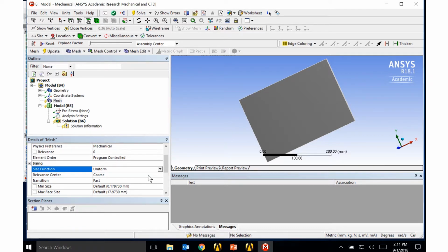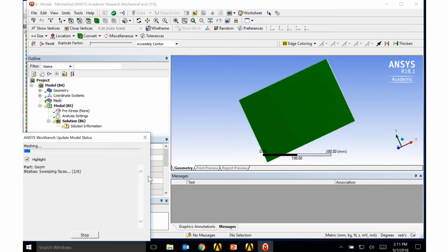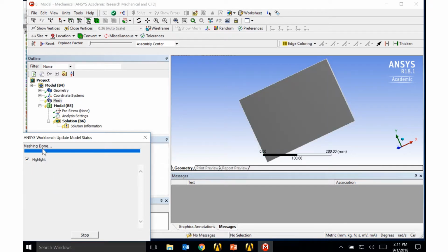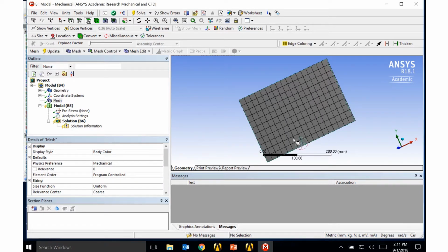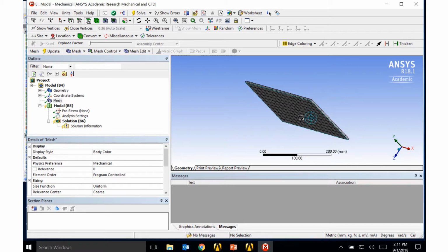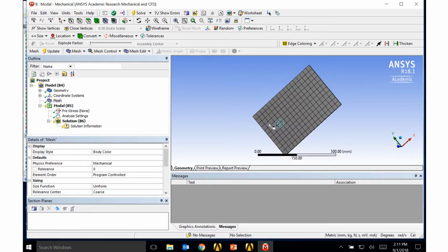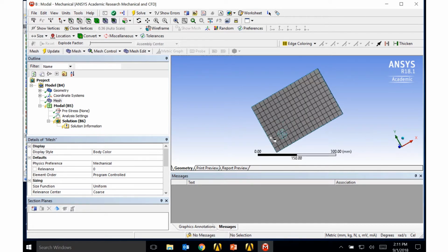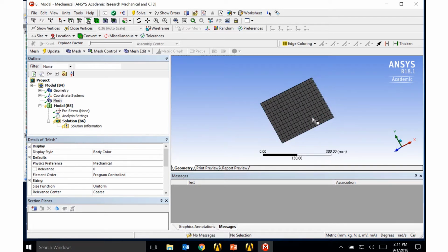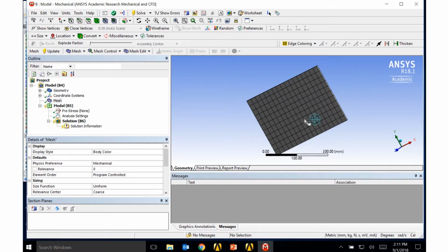and this can sometimes take a few seconds depending upon the size of your structure and the number of elements. But this meshing icon pops up, you can see the progress, and then meshing's done. You can come over here and look at your mesh, and for this model I'm going to let that mesh be sufficiently fine for the analysis that we'll be doing here. You can see that I got a green check on my mesh. Then it's done, and I'm ready to move to my modal.